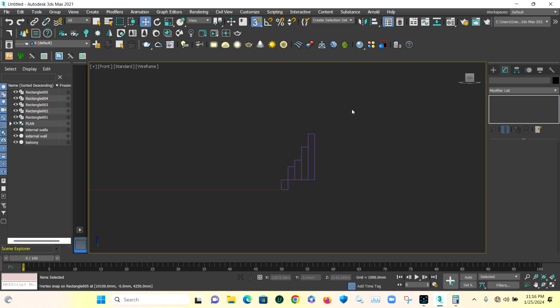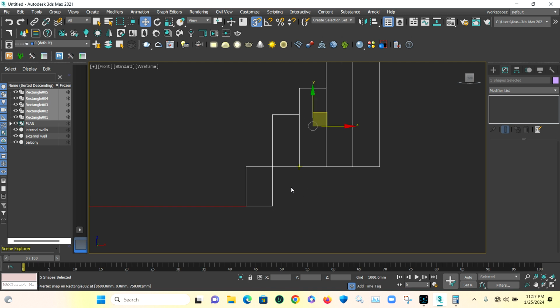I select them. Remember, group, select only what is needed. But in case you mistakenly select what you don't need, this is how you unselect. Let's say you just want to select this 4, but you mistakenly selected this 5. How do you unselect? You hold alternate on your keyboard, then take your mouse on top of that thing that you want to unselect. If you check, you see that the mouse changed from this to this. Once you are there, left click, it will unselect. Anything you want to deselect, hold your alternate, go on top of it, left click, it will deselect.